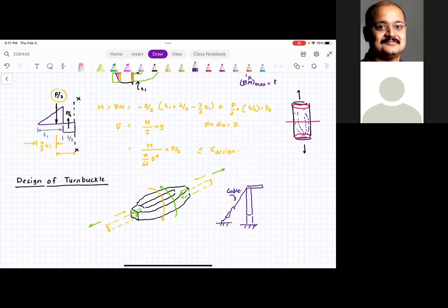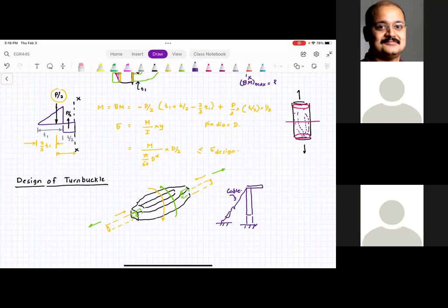Similar concept. I don't know if you work on cars. If you have slightly older cars that don't have a hydraulic tensioner, they usually have some sort of turnbuckle type tensioner, wherein the idler pulley gets moved top or bottom depending upon in what direction you rotate. So basically you can have a turnbuckle that will adjust the center.